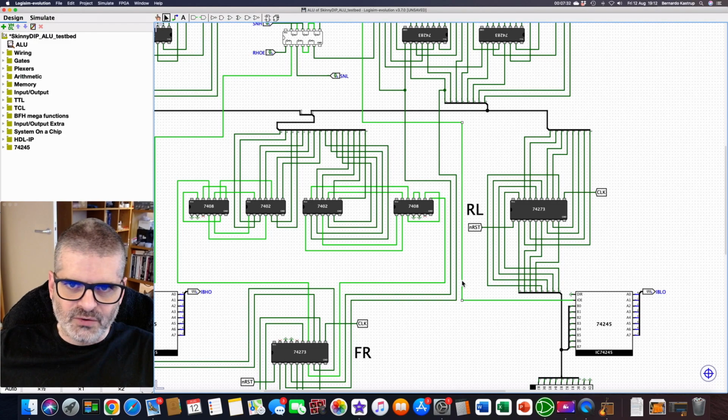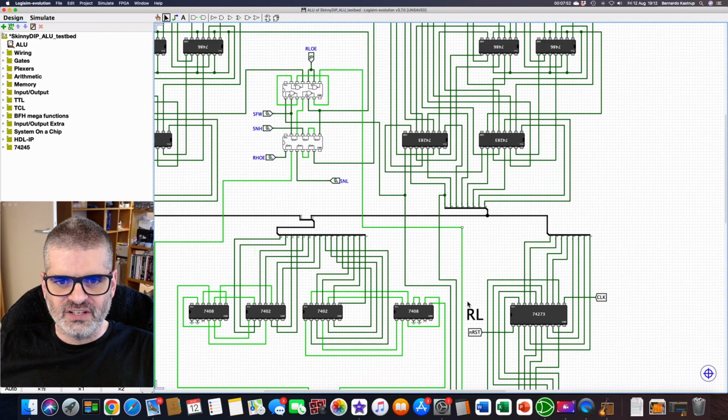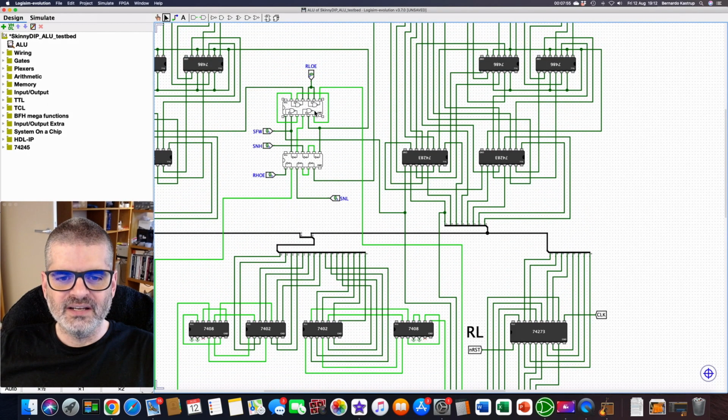When a trace branches out and goes to different places with a large fan out, you get a number of unwelcome things. You get a voltage sag, which a commenter taught me this word in the previous video. Thank you for that. I didn't study electronics only in English, so I didn't have a word for voltage sag, which is what happens when you have a large fan out and the chip that is sourcing the signal, in this case, this chip here, the 7400, has difficulty sourcing all of that current for all of the other chips that are getting the signal, and then the voltage begins to fluctuate. That's called voltage sag. There you go. Thanks for that. So there will be no voltage sag for this one. It's a fan out of 1.